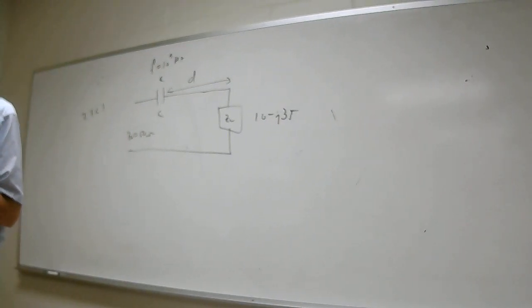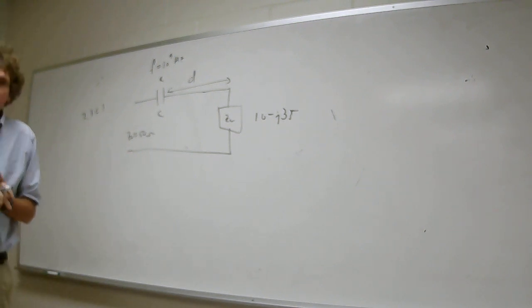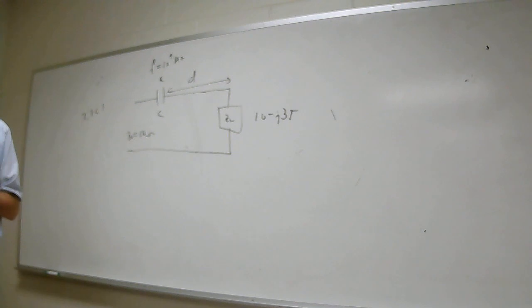I want to give you a tip too. Almost always, not guaranteed, but almost always when you talk about putting something in series, it's because we often have DC biasing requirements. What's the impedance of an inductor at DC, anybody? Technically it's J omega L. What is omega for DC? 2 pi times 0 is 0.